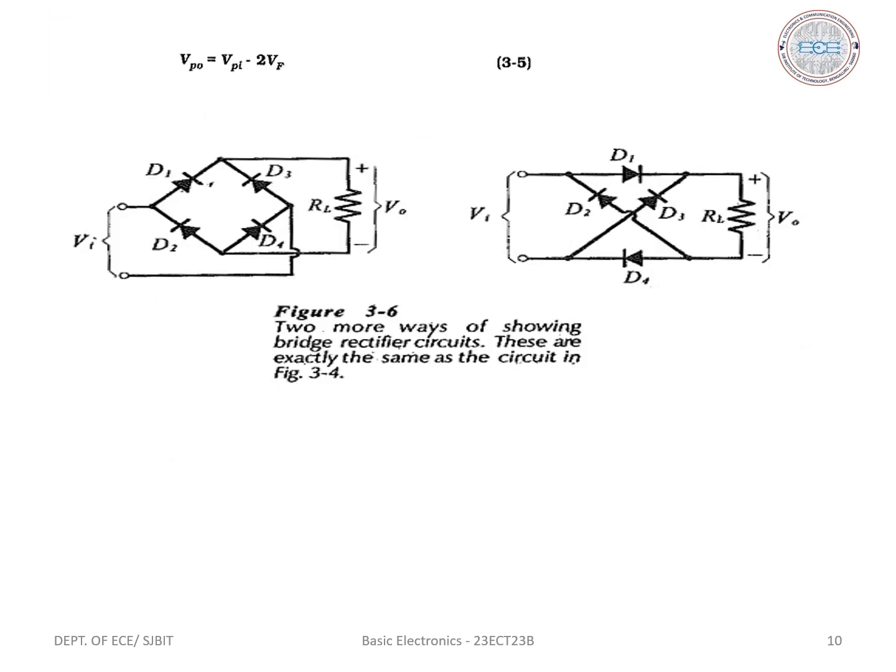Next we have the advantages. The advantages of the full wave bridge rectifier are that transformer cost is less, the output is twice when compared to the center tap full wave rectifier for the same secondary voltage, and the peak inverse voltage is one half compared to the center tapped full wave rectifier. Next, the disadvantages of the full wave bridge rectifier: since it requires 4 diodes, the use of 2 extra diodes causes an additional voltage drop, thereby reducing the output voltage.